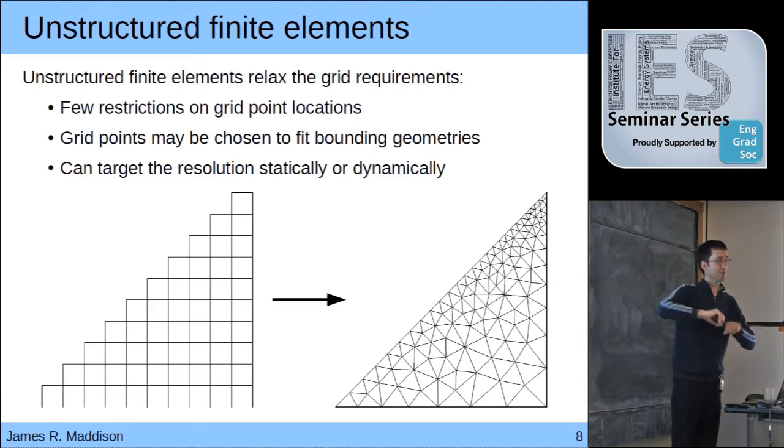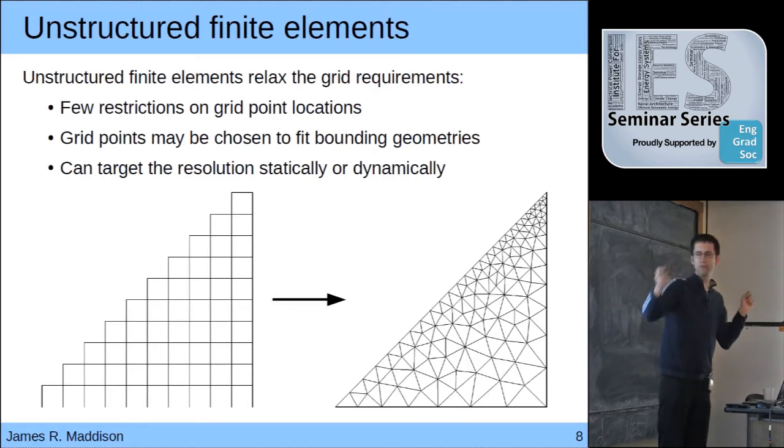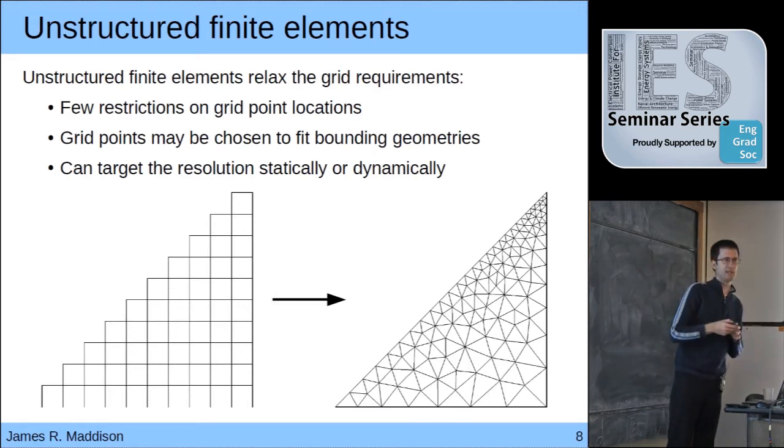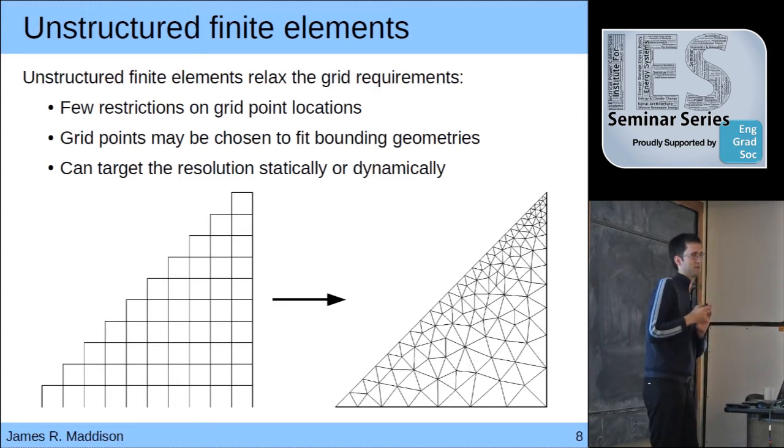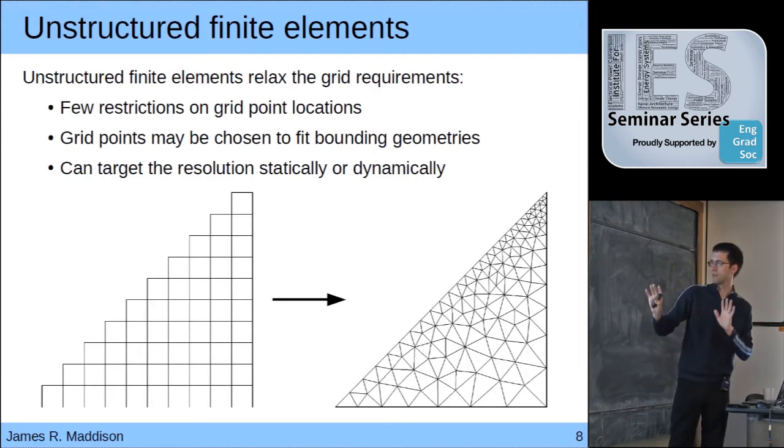Perhaps you hit an edge and you just say mask them out and say don't compute them, and then you end up with this, called a staircase representation of the boundary, and you can have problems associated with that. You can at least see even by eye it's not a very accurate way to treat the problem. And you can imagine how this gets worse with complex boundaries.